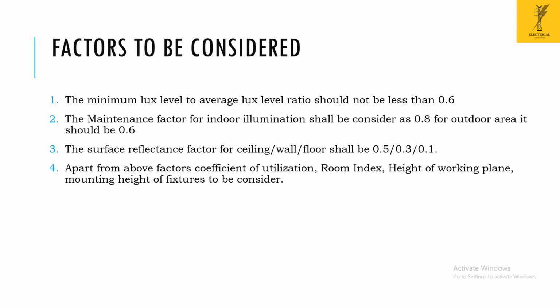Apart from the above four factors, the coefficient of utilization, room index, height of the working plane, and mounting height of the fixtures are also to be considered. All of this I will show you practically in Dialux.